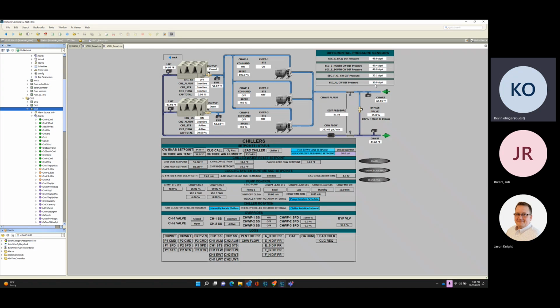I again can't see the details very well, but is it fair to say that you have a single differential pressure set point of, let's call it, 20, and if any of those listed in the upper right hand corner start going below 20, it starts to ramp up? So there's an algorithm in there looking for the lowest differential pressure reading, and that's the one it wants to make sure it maintains above set point, which is 20 right now, correct? Correct. It's exactly right. Thank you.